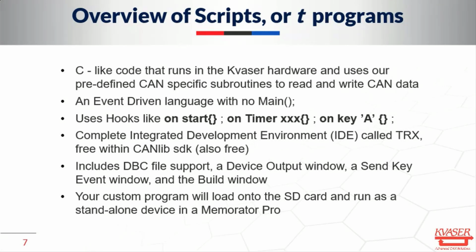It allows you to write C-like code that actually gets downloaded and flashed onto the Kvaser hardware that executes when powered from the CAN bus, and it's an event-driven language that allows you full control of the logging process and allows you to totally interact with the bus as well as log, so you can simulate a failing device and log the conditions that the ECU goes into to handle that failing device or handle that actual log condition.